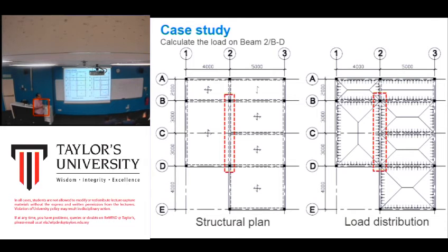Right. So you need to draw the areas into which the slab divides itself. Because this is a two way slab, of course it will be in the form of a trapezoidal area, and this one will be a triangle, right? So which area of this slab is connected to this beam? Here, one trapezoidal shape and two triangular shapes.